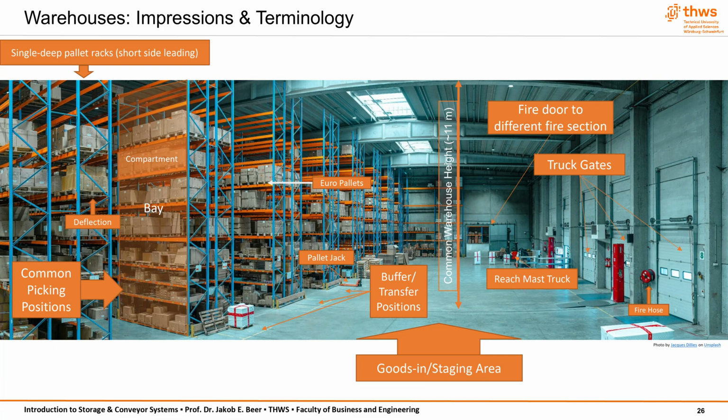These tolerances are typically specified by pallet manufacturers, rack designers, or occupational safety standards. In the example we're looking at, however, the deformation seems to be approaching, or possibly even exceeding, those tolerances. Why is this important? Excessive deflection can lead to both safety hazards and operational inefficiencies. In the worst-case scenario, a pallet under too much stress might break. If that happens, the load could fall off and drop from the rack, potentially causing product damage, destruction of warehouse infrastructure, or even personal injury.